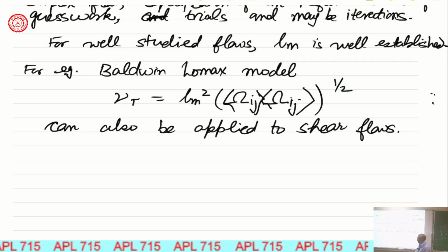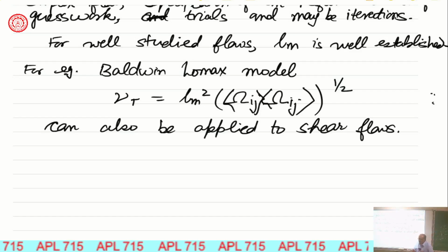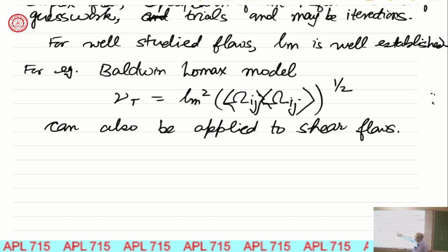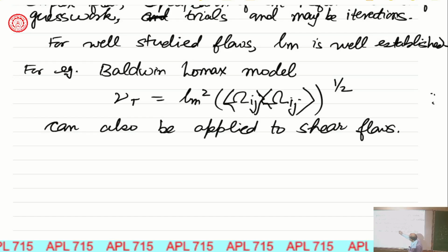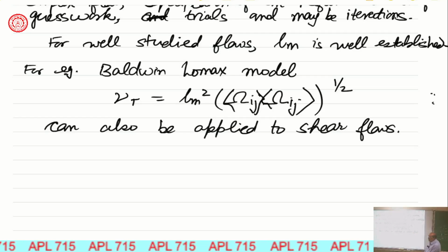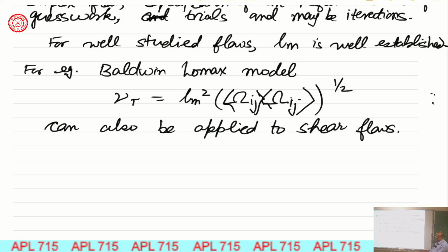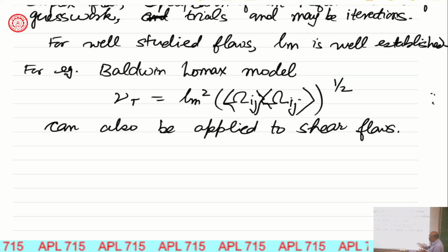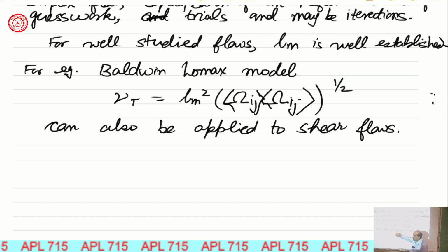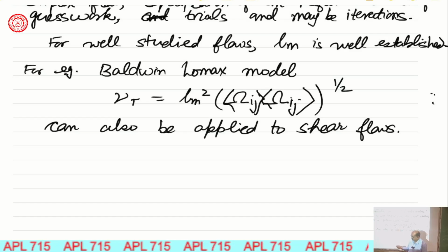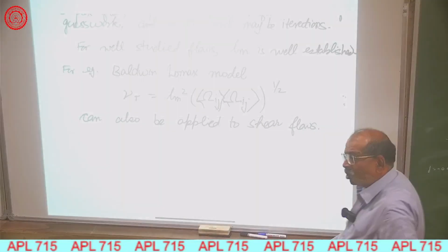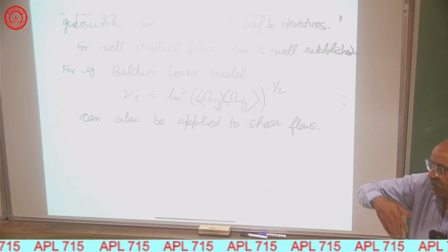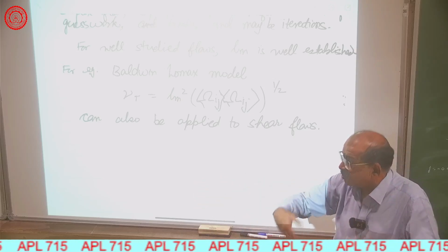But if we try to look physically at whether there is any issue with the eddy viscosity, here again we are writing the eddy viscosity as a function of the mean velocity. Mean of omega ij is the mean velocity gradient related to that. So the turbulence is coming only if we are able to put it in some form of Lm. Otherwise, we are only using the mean velocity, which of course has to be physical because there's a transfer of energy from large scale to small scale, which causes turbulence.